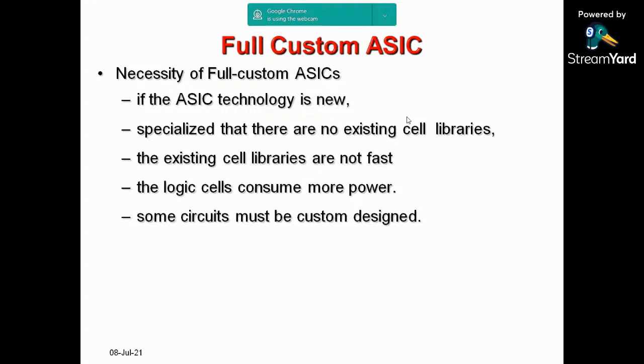A standard cell, where the p-type layer and n-type layer are characterized and tested. The technology information and the timing of the cell, everything particular to the cell, will be there in the library, like a software file, a library file. You use the library file to use all the available cells, like your C functions. You might have studied the built-in functions available in C. Similarly, we have built-in cells, where you can drag and drop, or the tool automatically picks up the cells.